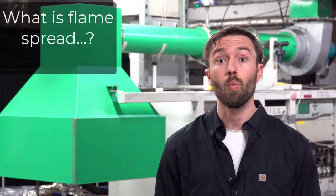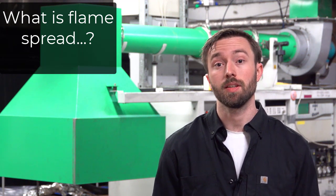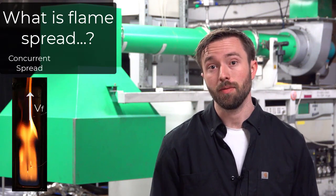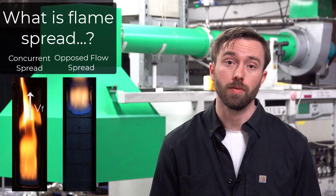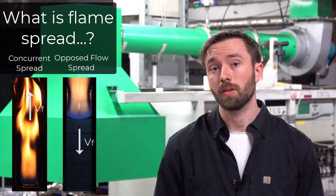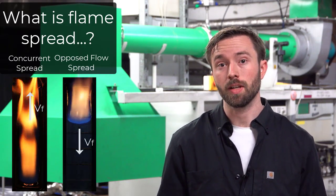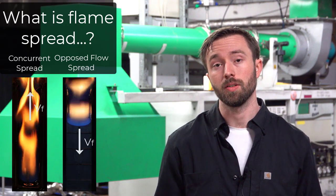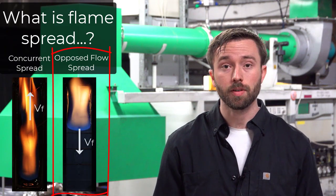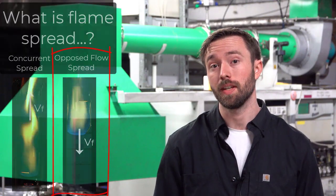So let's start with the question, what is flame spread? The rate at which you get flame spreading over a solid fuel is generally broken into two categories. One being concurrent spread, or spread in the direction of ambient flow over the fuel surface, and opposed flow flame spread, or spread in the opposite direction of ambient flow. Each of these categories of spread has its own significance in understanding fire dynamics, and both are integrated into the regulatory testing system for material flammability. In this study, we'll be focusing on opposed flow flame spread in an effort to study a steady state process in which we can interrogate the relevant physics with a high degree of fidelity.